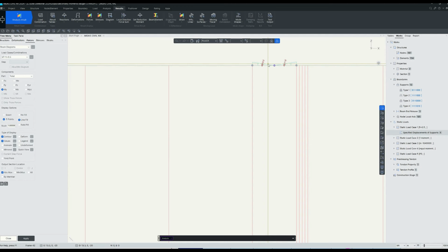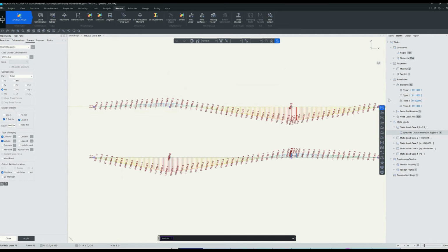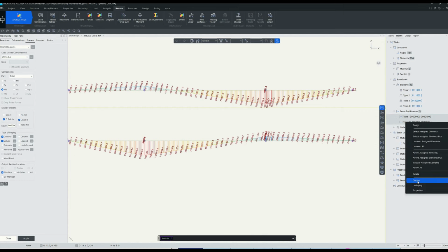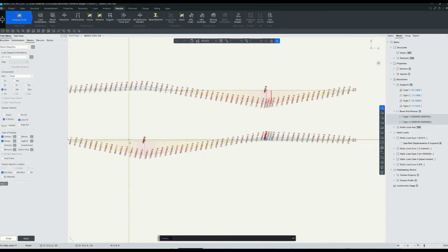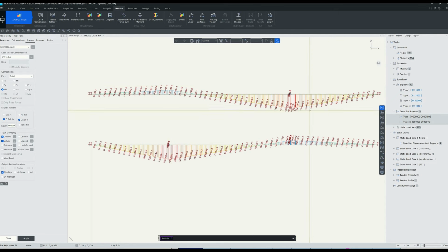You also can assign rotation load at the end of the beam where the hinge is inserted. And I got those figures. I'll show you beam release. It's not possible to see, okay? So I take these figures, put them in my Excel with the length of the element, and did the procedure that I just described.